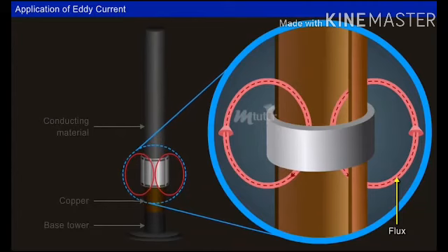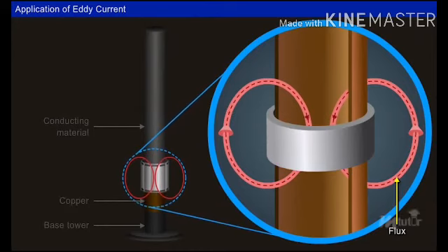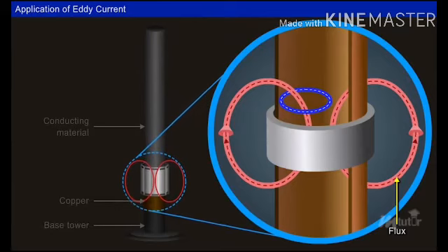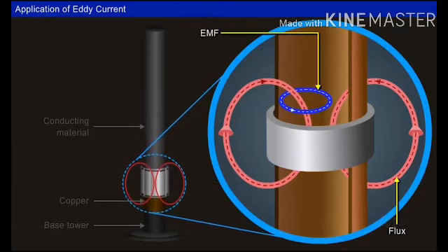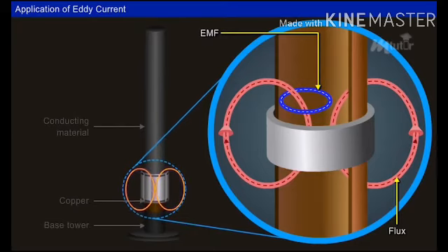The magnetic fields due to the permanent magnets travel down as the gondola drops fast from the top of the tower. Once the gondola reaches the copper part of the tower, it starts to slow down because, as per Faraday's law of electromagnetic induction, an EMF is induced in the tower due to the change in the magnetic field linking the tower.